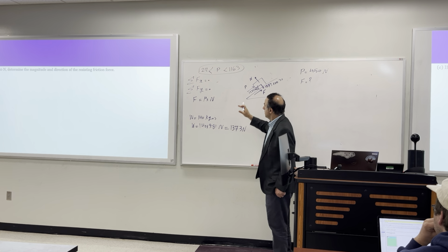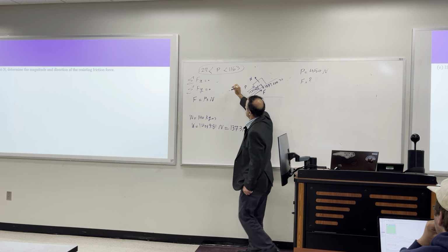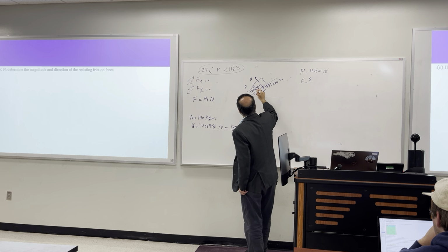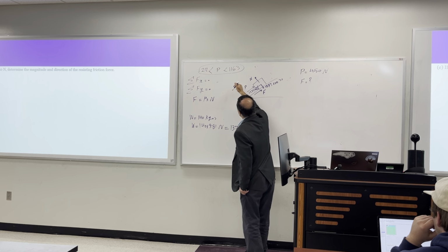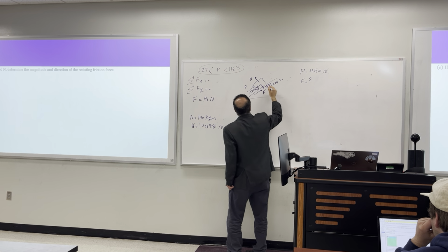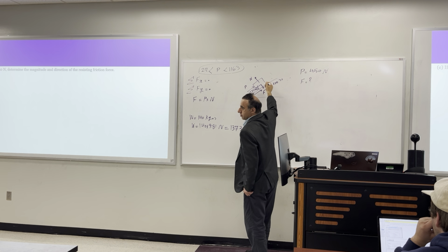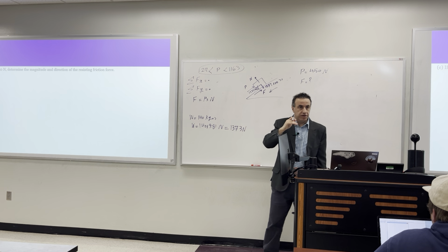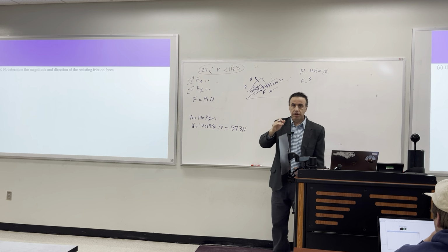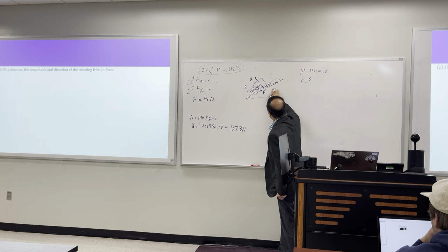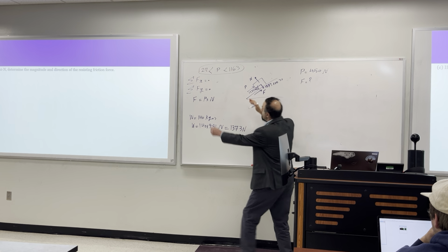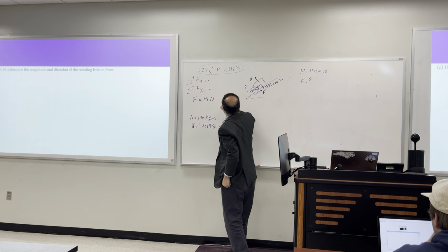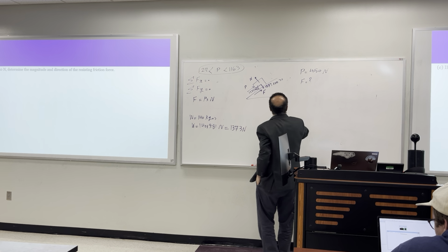So my P, because it's less than this, when we get to this point, my F is going to be opposite direction. My F will be in this direction. It's going to resist against movement. But now we are not in that situation. We are in this range. So friction is going to help us against movement. So friction is going to be like this.